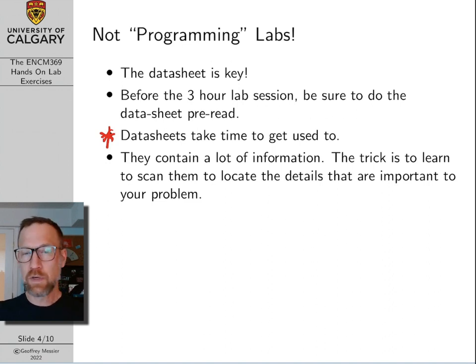When you open up the datasheet for the first time, you're going to see it's hundreds of pages long. And I don't expect you to read it from the very beginning to the very end. In fact, one of the skills I want you to develop in 369 is to learn how to read a datasheet. The way you learn is to scan the introductory contents, the table of contents, get an idea of what's in the document, and then know specifically what sections to dive into for the particular problem that you're trying to solve.